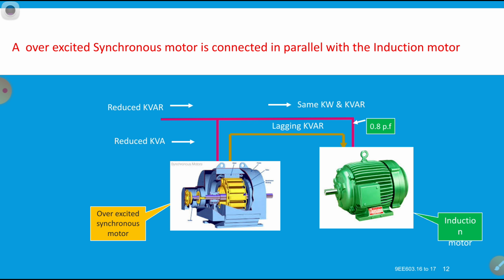here we are taking the kVAr, reactive power. Normally the induction motor always draws kVAr, reactive power, from the supply at lagging power factor. Due to this, what will happen? It will draw more current in the line. At the same time, the performance of the motor may not be at its rating, reduced by some percentage due to drawing the reactive power from the system.